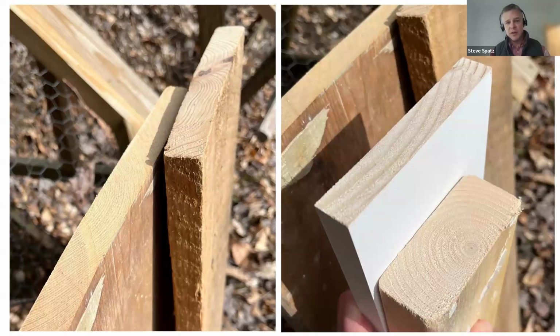And so the dimensional lumber that we're working with now is just as susceptible to moisture loading because of the amount of sapwood and the carrying capacity of that wood to retain water over time, compared to older growth, slow growth lumber that has tighter growth rings, more hardwood rings that are not going to take on as much moisture, and there's more stability in that lumber as a result.